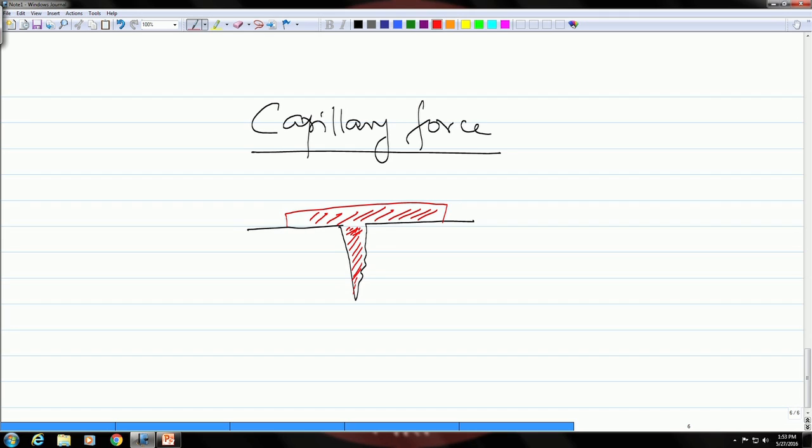And it is all over the place, because you have a spray can which contains the dye and you spray it over the surface. So, the whole surface will be covered by this red colored dye, and if there is any discontinuity, any flaw or defect, this dye will be sucked inside by the capillary force.